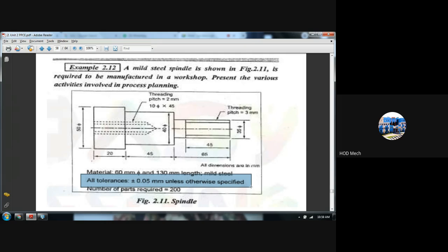I have reduced the diameter from 60 mm to 50 mm. When checking, they will check using the required measuring instrument. Right? So when checking, the tolerance will come: plus or minus 0.05. Okay sir, it is within this. Even if it is not exactly 50, it is acceptable. Then the component will be checked again in inspection. In inspection, they will check whether the machined area is according to the dimension required, or at least within the dimension and tolerance specified therein. This is how it goes on.